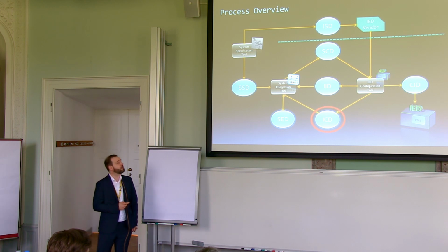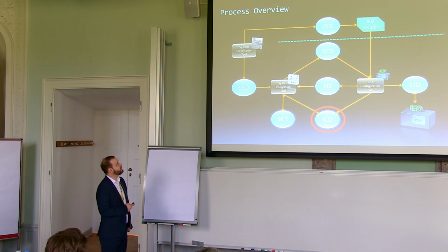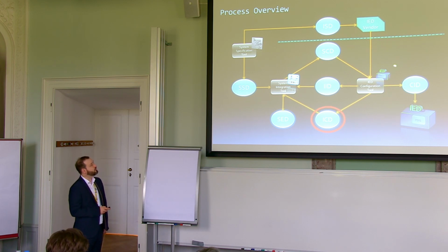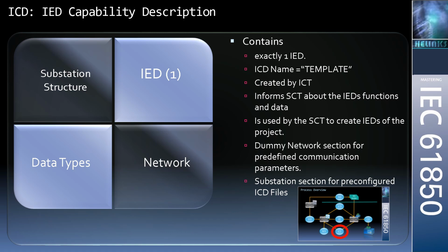So when you have an SSD file and you hand it over to the system integrator team or to an external system integrator, the next thing they will need is an ICD file or multiple ICD files. And these get produced by the IED configuration tools and are consumed by the integration tool. So these have some more requirements.